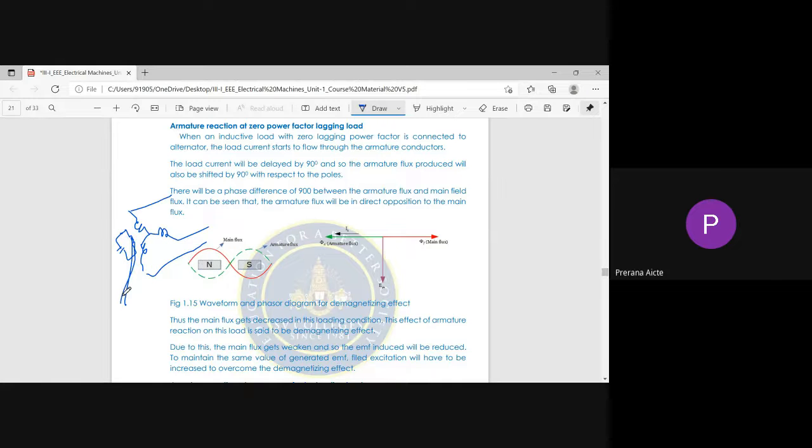It is in a rotor generally. The rotor is connected to the prime mover and runs at rated speed. By giving a rated field current to the field winding, the generator builds up rated voltage across the armature terminals. When load is connected, a load current starts flowing through the armature winding.